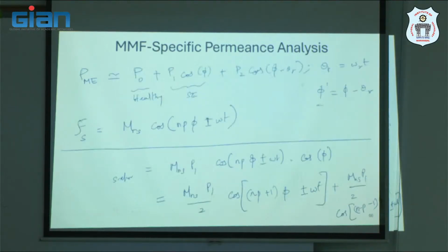have just taken one term initially in one direction and one term in the other direction. And we went from stator to rotor, which started with the static eccentricity function only, and we went back from rotor to stator, we just chose the dynamic eccentricity function only. If you use all of them, you can see what is the impact.